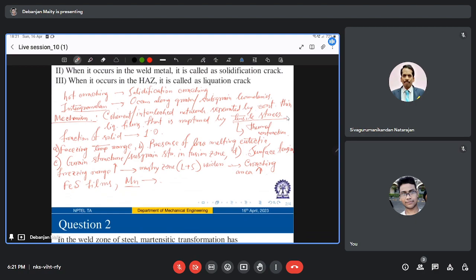manganese. What it will do in iron is form preferential globules of manganese sulfide. Okay, these are kind of harmless. So unless you are adding this manganese intentionally, if there is sulfur present, it can produce thin iron sulfide films, and the steel is more prone or susceptible to crack formation, right?